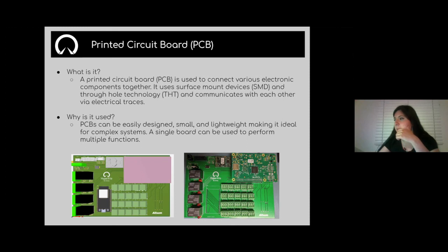And we're also just going to be doing some rewiring of the terminal blocks because you see all the traces under it makes the connections fixed. So we're just gonna change some around, especially between the two MCUs. In changing some of the traces between the ESP and the Raspberry Pi, we could eliminate some external components. So just those types of optimizations as well. And also the way we're going to trace things for the second board, it's going to be a little bit better so we can avoid crosstalk.